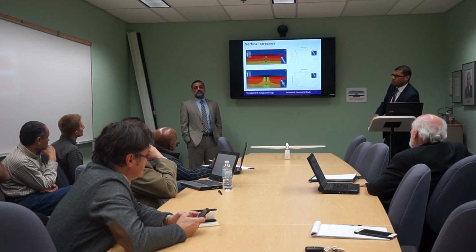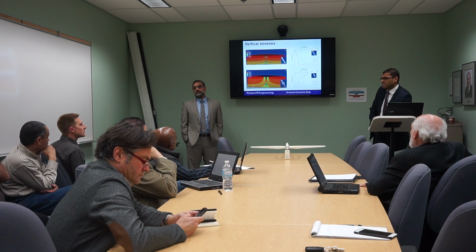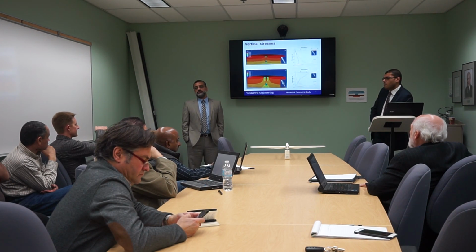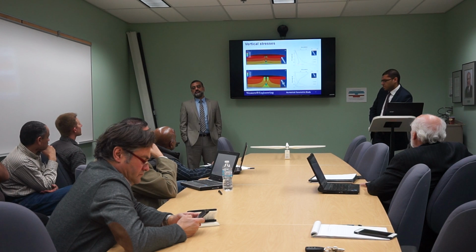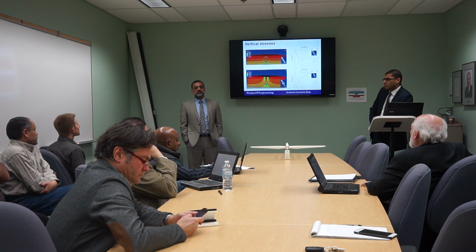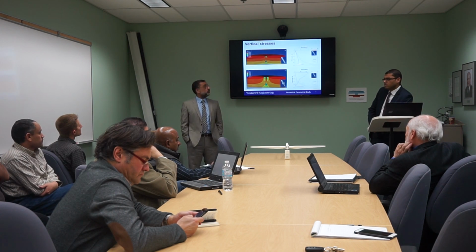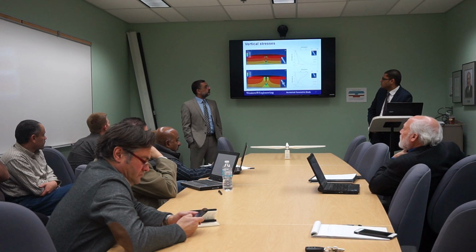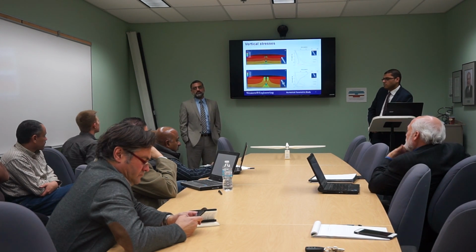Usually between 3 and 5 meters will be enough. We have done, as I said, a sensitivity analysis, so it was good. And you noticed that as you changed it, it didn't really affect the results? Remember, the main load here is lateral, so basically it's this condition. It would be more severe here. Yeah, and I could see the bottom of the stress field, and it doesn't flare out.